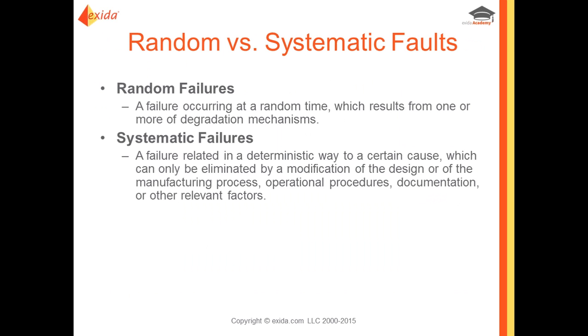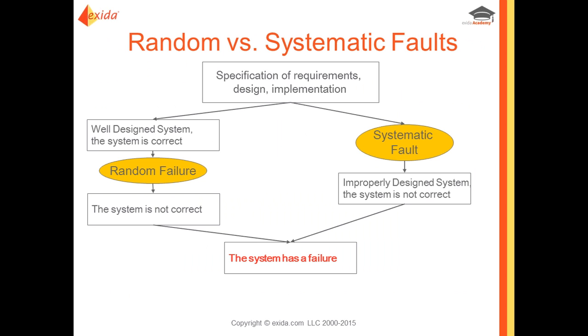So if you calculate the probability of failure on demand to be 5 times 10 to the negative 2, you would see that that falls into the SIL 1 level because it's over negative 2, or 10 to the negative 2. So you would have to go through this chart and find where you fall, or you can find where you fall and decide which SIL level you would like.